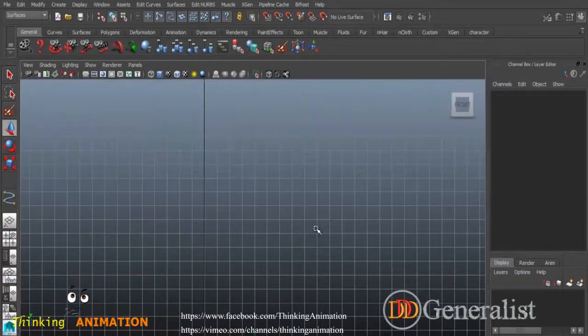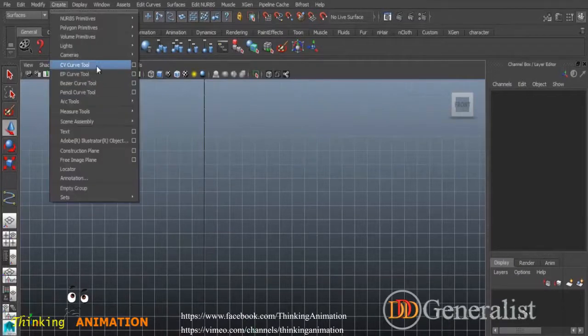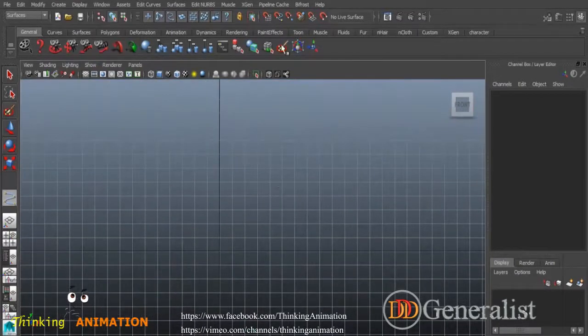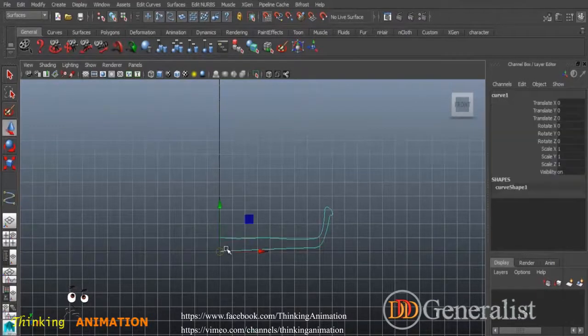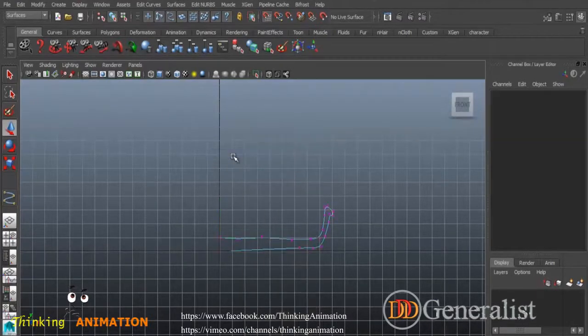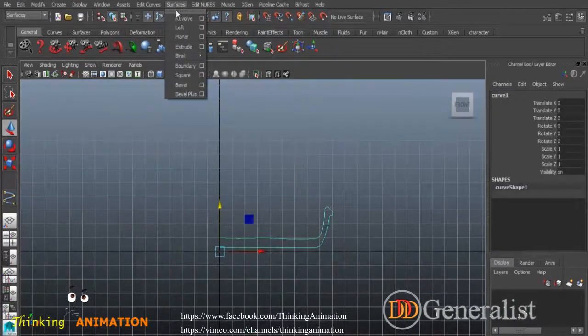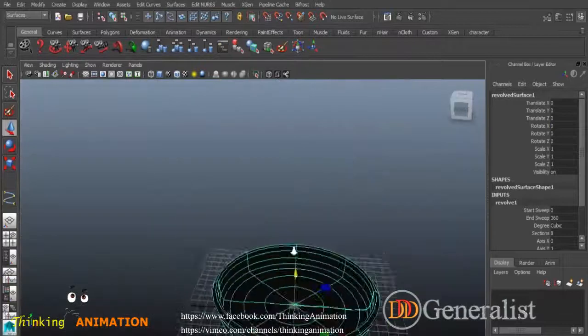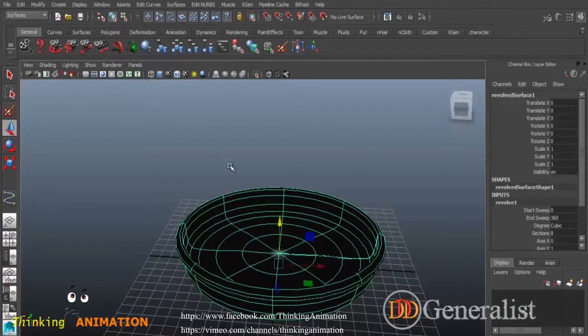Okay, you select all of them and delete. So I'm going to give you another example. If I create something like this, if we turn snap to grid on, select this one, turn it off, you go all the way around, something like this. If you create something like this and again snap to grid on and press enter, right click and choose the control vertex and move this a little up, something like this. And now select the object mode, select the line, apply the revolve, and this way you get a shape like this. But what if you apply the scaling option?